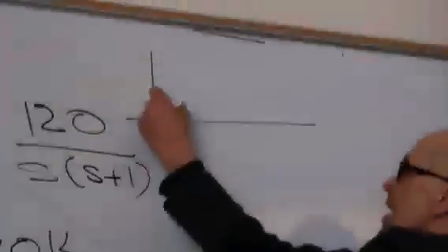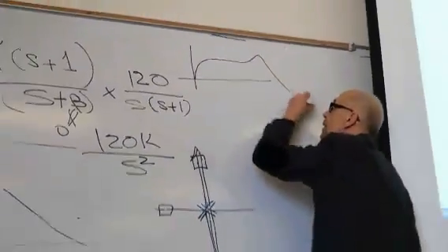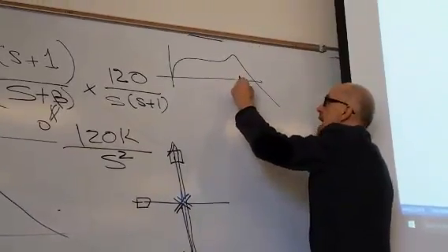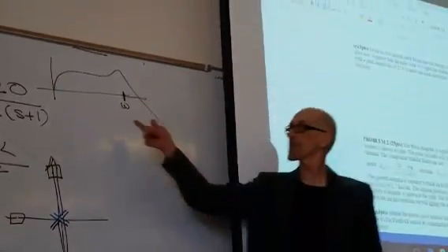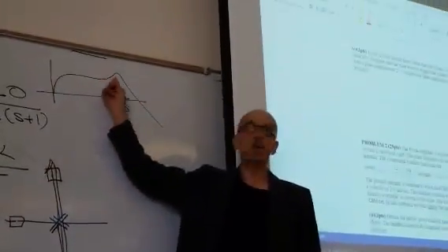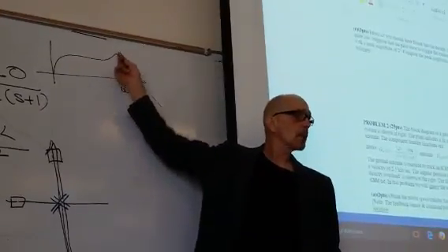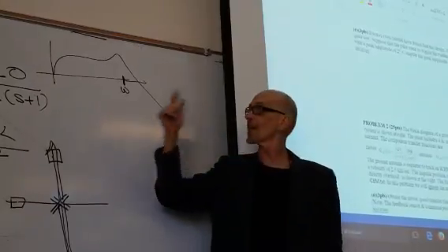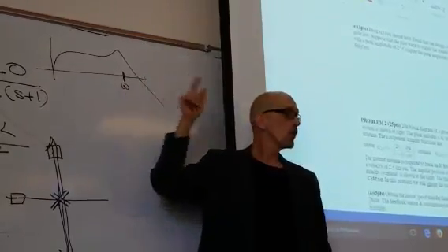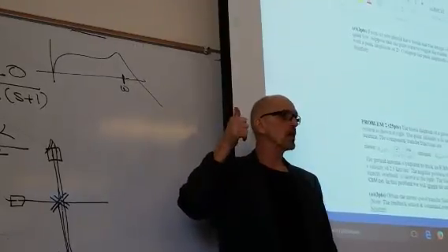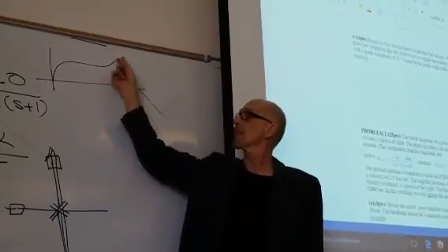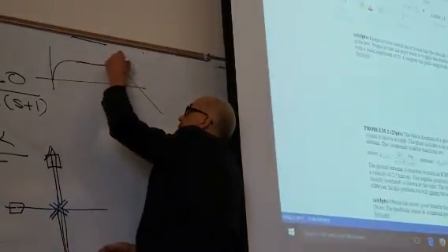This plot that we had up here before, I've done this plot so many times. Here's an accelerometer's FRF. Why do you not want to be measuring accelerations at that frequency? Because a given acceleration at this frequency isn't going to scale like a constant. It's going to be amplified by the actual sensor. So you may have a very low amplitude here for true acceleration, but when you measure it with an accelerometer, because you're at the accelerometer's resonance, it's going to be magnified by this many dB.